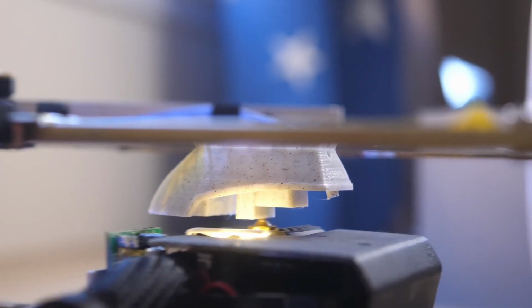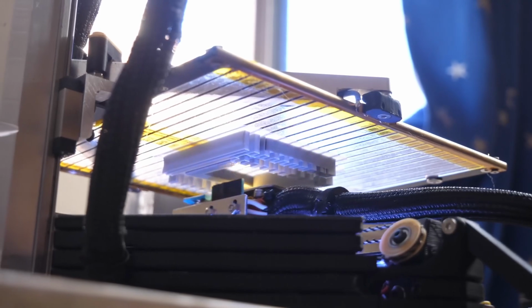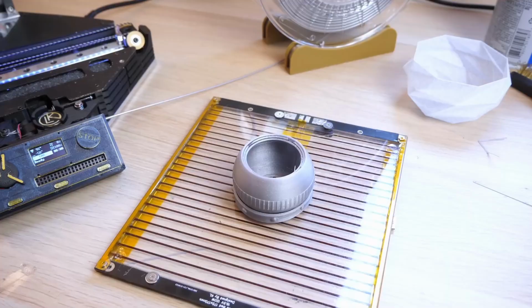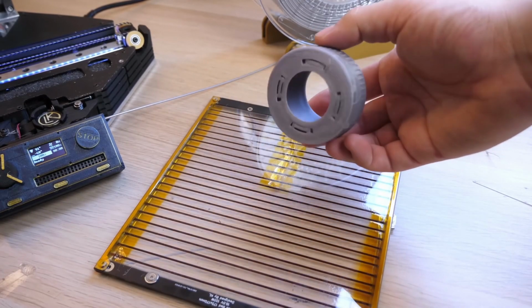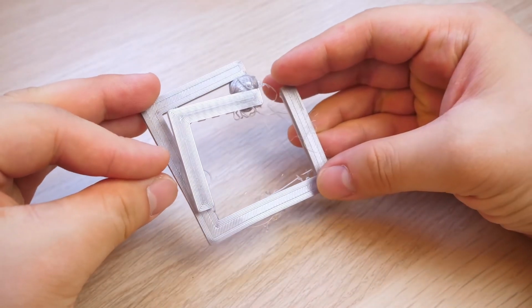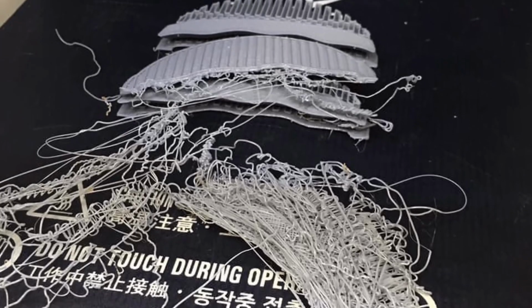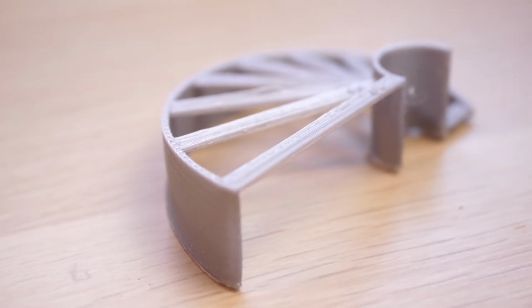Because this printer prints upside down, one of the most obvious questions is does the print fall off the build plate? The answer is no. The prints actually stick very well to the sheet of glass. And upon cooling, the prints also automatically release themselves. The only time where I had prints falling off the bed was due to warping and the nozzle knocking them off. PETG, or in this case PLA, the print is still going to fail, even if the printer is printing right side up.